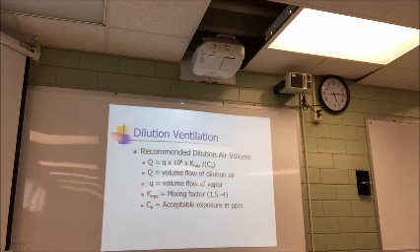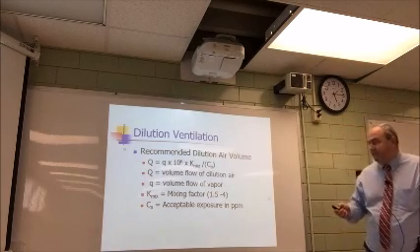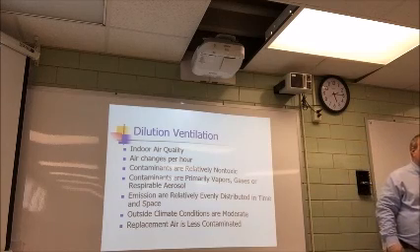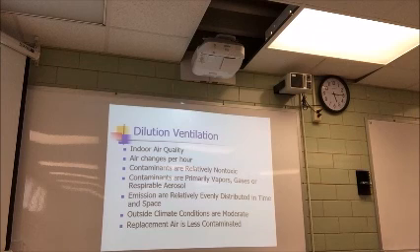Yeah, the ACGIH or OSHA PEL. And I will always, again, in the problems, tell you what you need to use there for your acceptable limit, okay? But in the absence of data, you'll go use the regulatory standard, okay? Again, formula, this tells you the volume of airflow that you're going to need. So it's very valuable. Dilution ventilation, again, normally indoor air quality, contaminants are relatively non-toxic, and that's the